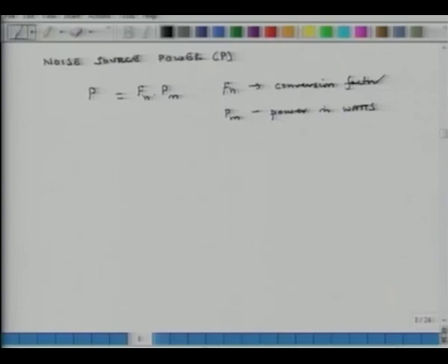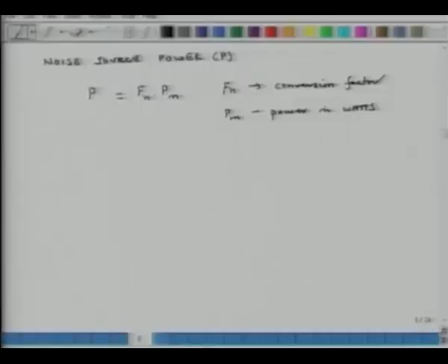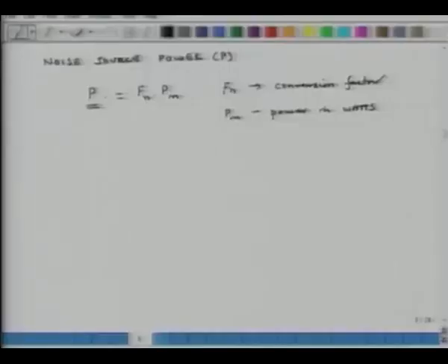So in the handout which you have, if you look at table 14.1, what you have is different conversion factors for broad types of machinery. For instance, compressors, you have 1 to 100 horsepower, and if it's a low power compressor, then it's 3 times 10 to the power of minus 7, and so on and so forth. So they are standard. Some of these data are there, you can extract that data and get a broad coarse understanding of what is the noise source power level emitted by a particular type of machinery. You can figure out from that.